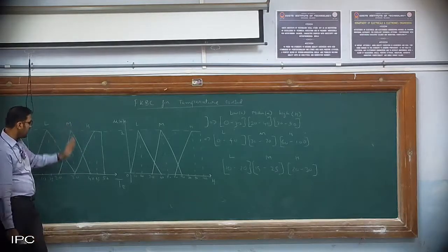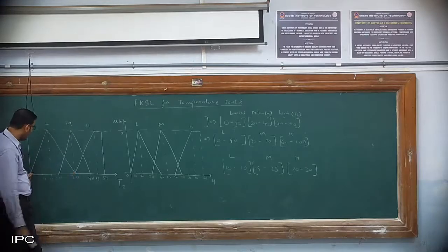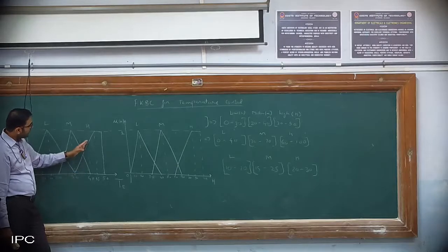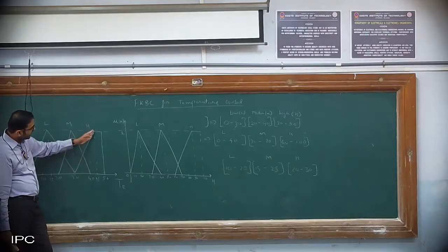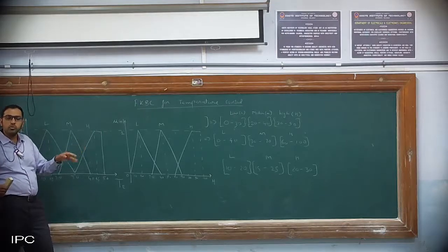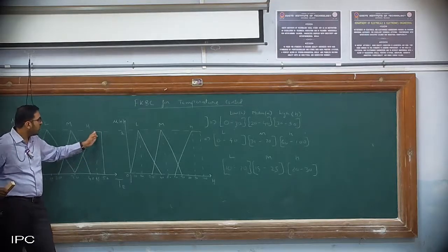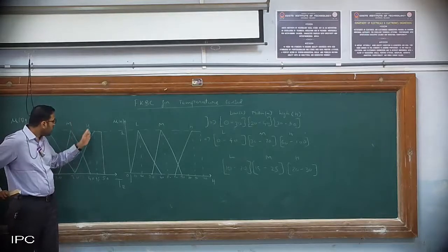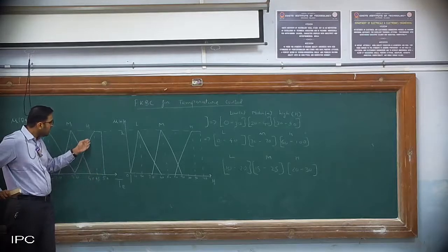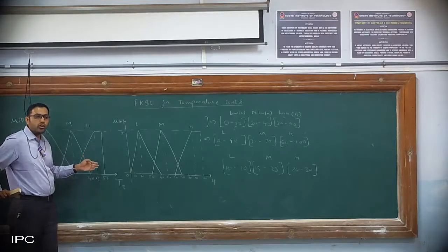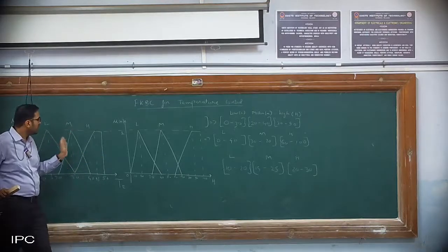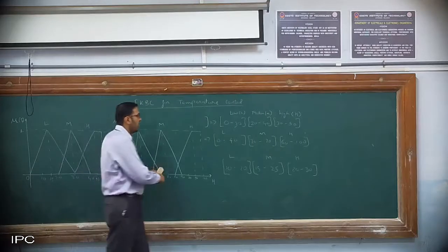what we are saying is high temperature. So 30 degrees has a degree of membership of 0. As we approach 40 degrees, the value goes on increasing. Till 45 it increases and reaches its peak value. 45 degrees and 50 degrees will not make much difference because both are extremely high temperatures, so it should have a degree of 1. We cannot go on decreasing, because that would mean the degree of membership is reducing, and for high temperature the value should remain at maximum. Okay. So similarly we have done it for humidity also.